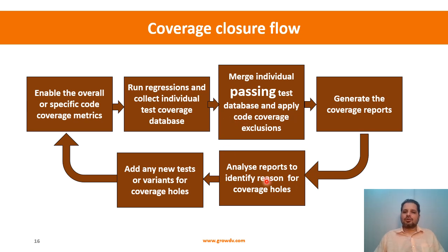If it's code coverage, you obviously talk to the design team to understand what you need to be doing in the test bench as to what type of stimulus you need to create to exercise that uncovered area. And if it is functional coverage, obviously you have defined it to certain requirements. You are expected to know what changes we need to make in the stimulus. Do we need to increase the distribution for certain stimulus generation, or are we missing something, or do we need to create some corner case by adding some additional weight and orchestrating across interfaces to make that particular scenario happen.